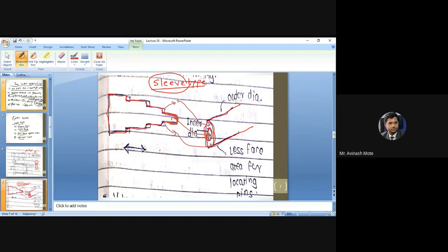This elongated part will go inside this hollow area, and these two surfaces will rest on this side area. And you can easily eject the product. So your question will be, why is there a uniform section rather than this step section? This is because you can use the same kind of sleeve for different products with different diameters. If the diameter is more, this cross section can be used. Again, for more diameter, this cross section can be used.